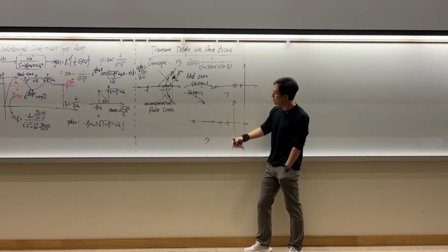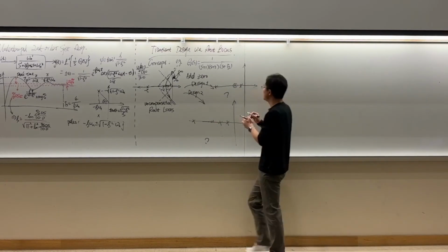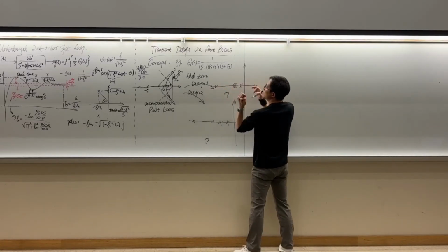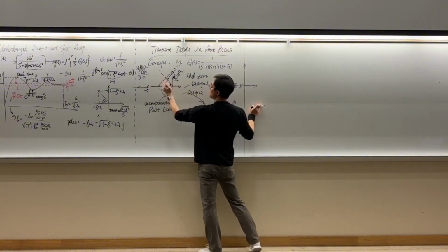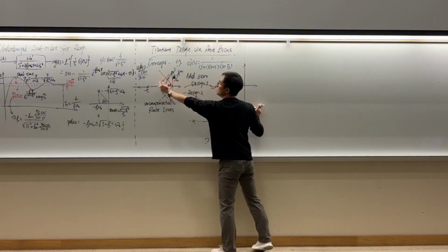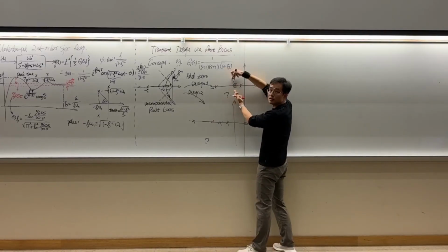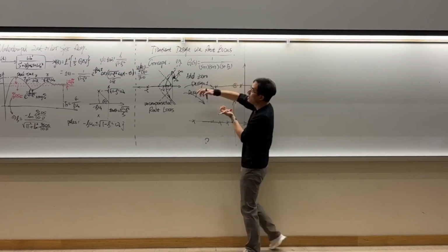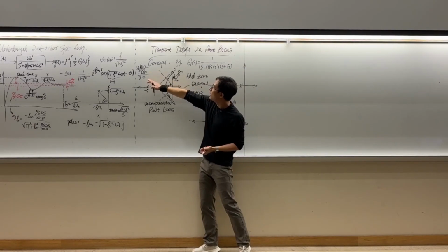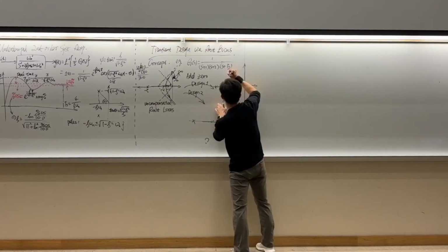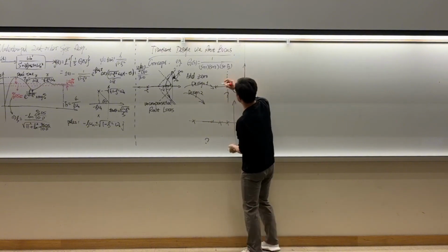This 0 is a little bit to the left. Then the root locus is going to become, so you can do it again, right? For this system, the root locus, you can again calculate the centroid and the asymptotic angles. The centroid of this one is what? It's here in the middle. And the asymptotic angles will be plus minus 180 divided by 3 minus 1, so it's going to be 90 degrees. This is your new root locus.